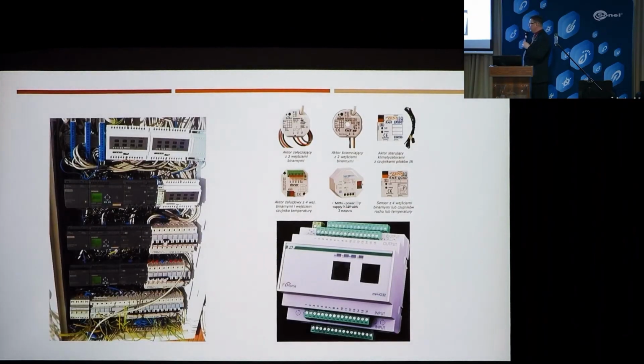The problems start in cases like these. You see, sometimes you simply can't disconnect that circuit. And of course, if something is connected to the circuit, even when that circuit is de-energized, it will affect the measurement. The loads connected to the installation will complete the circuit for us, and the results will simply be false, or our instrument may even indicate some kind of short circuit. That's still not too bad, because in this case it will only add to our frustration that despite our efforts, something was still left connected.